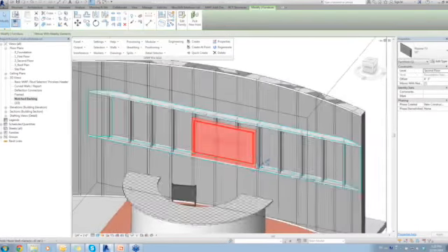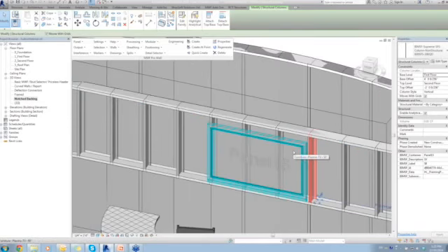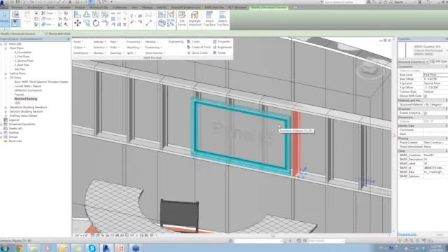I'm interested in placing some notched backing on this member, which I can see is member S5, and I want to send it all the way over to member S8. So these are the basic MWF names that all of our studs are given for this exact reason. I need to know what studs I want to place my backing on.